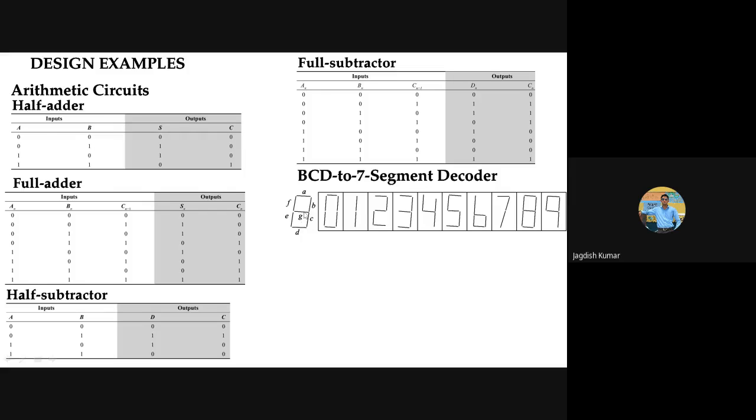display? A 7-segment display has 7 LEDs. Let us see it as made up of 7 linear shaped LEDs. Then you have one LED here, second, third, fourth, fifth, sixth, and 7th. Based upon which of the 7 LEDs are glowing, we have these numbers here. For example, to display 0, A, B, C, D, E, F all should glow. That would give you 0, right? For 1, only B and C should be switched on. That will give us 1.